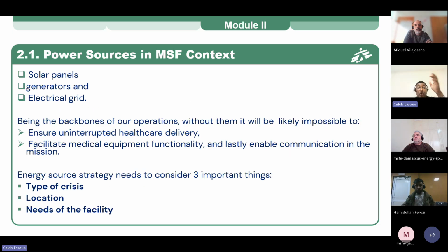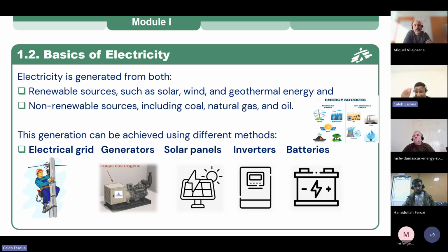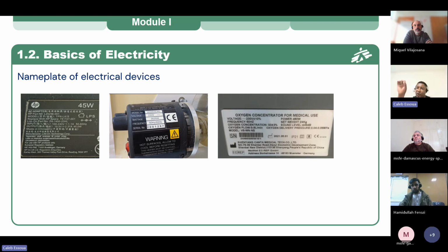Yes, you go directly to the lab. Okay, what is listed? You check the nameplate. You see if you have the power already. You just write the name of the things and you write the power in front. If they don't give you the power, just check the voltage and the amps, and after you use the formula that we show you to do your calculations, then you can get your power and you introduce it in your generator